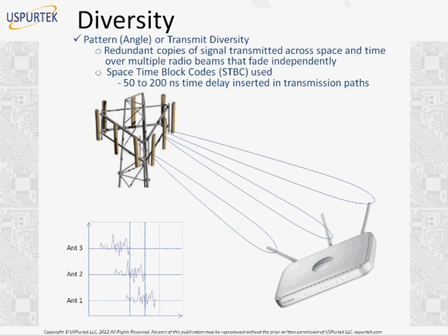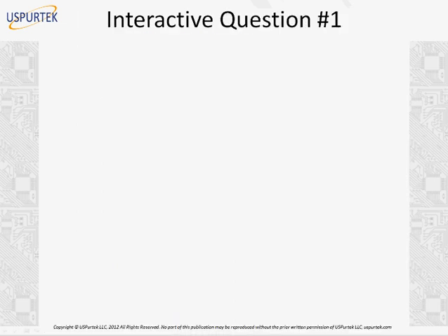Polarization diversity is inherently implemented in circular polarization. This we have seen in the previous webinar too. So the idea here was to highlight that fact over here. So we definitely have diversity inherently implemented in circular polarization. So if our cellular systems could implement circular polarization in their cell towers, then on the handset, if you lose the vertical component but you still have the horizontal component, your fading effects will be reduced. Very good.